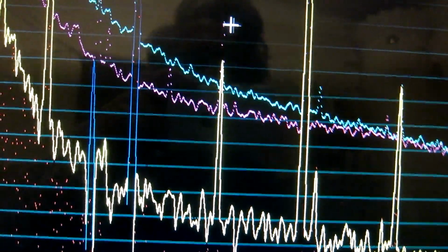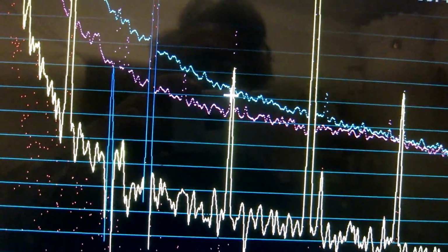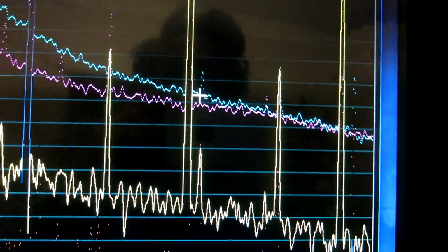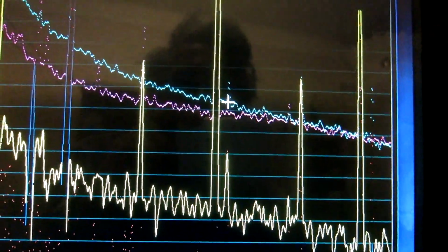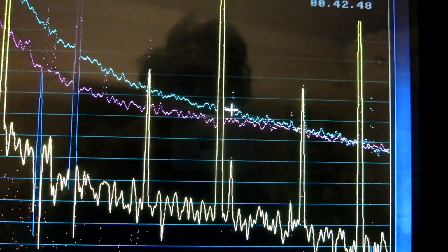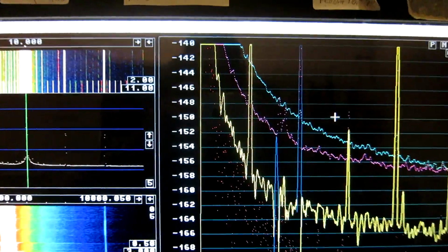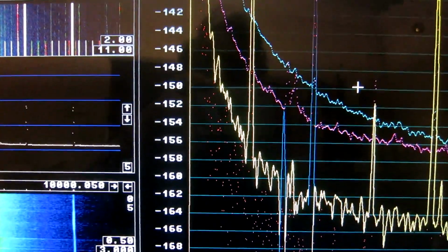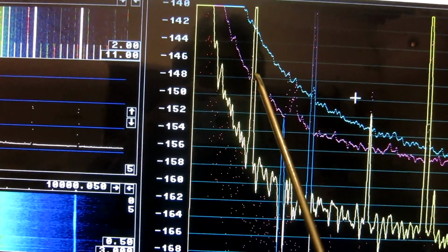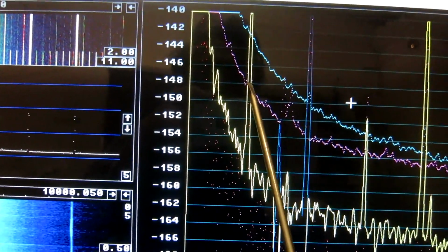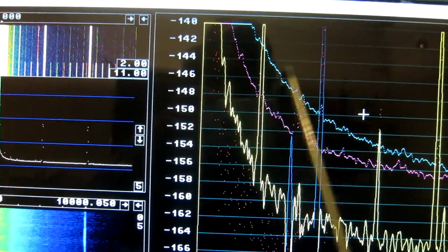But here the red dots go much higher than the green dots. But here there is some spur which is not an overtone of mains, and that is stronger in channel 1. It's pretty clear that the local oscillator of channel 2 is much better than the one in channel 1. You can see the phase noise differs by about 6 decibels at 50 Hz.